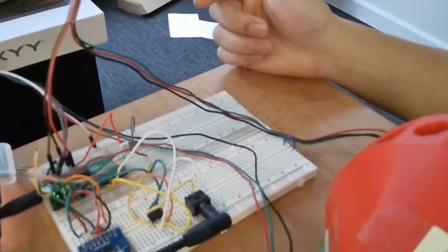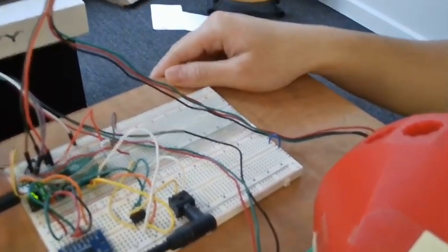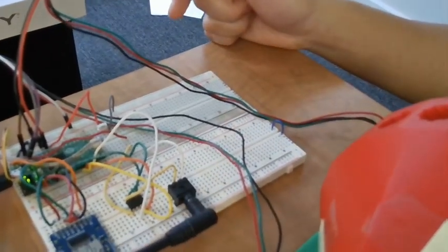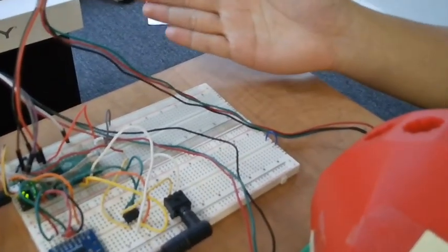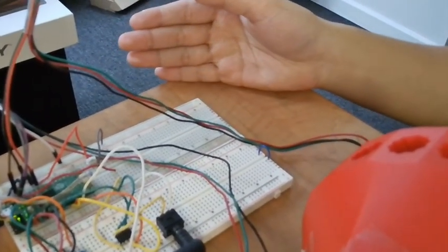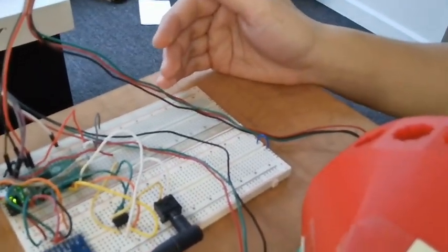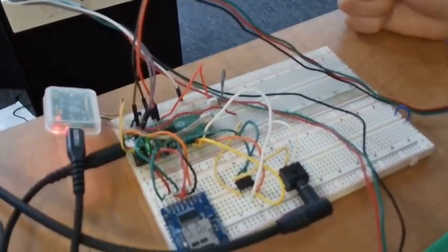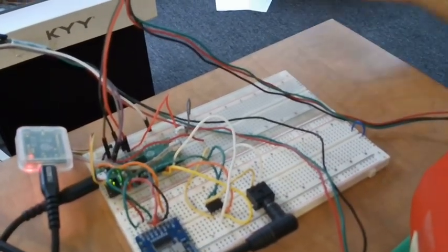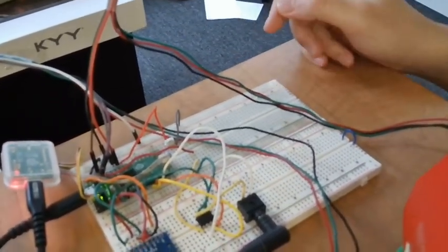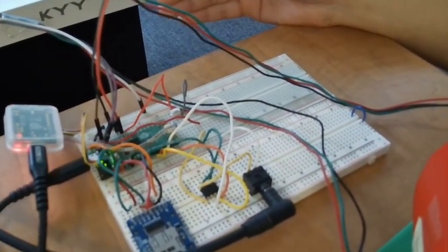Because of that, the fidelity degraded a little bit, but we countered that by using a guitar amplifier, which did improve the fidelity quite a bit, as well as brought the volume to a reasonable level for recording. We also have a serial debugger, which we use to set up a serial interface to control the flow of the program, namely starting and stopping the recording, choosing what primitive we want for playback, as well as specifying the angles.